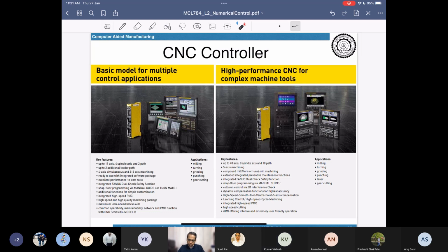Those were the earlier days where people were punching the program directly onto the machine, but it is not required. But the machine has all that capability. You can write a new program, but those are limited to only the very basic instructions. You can write the part program only for very small motions, which are a combination of linear and circular paths only. Whenever it comes to 3D interpolations and 3D geometries, all those programs are generated by the CAM software.